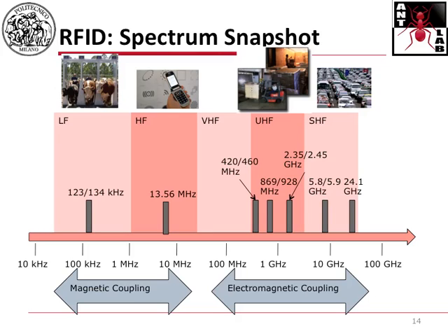Each one of the specific frequency bands has specific features in terms of, I would say, two performance measures. The first one is what range you can achieve in that frequency range, meaning how far can you go from the reader to the tag. And the second one is the specific technique which you use to scavenge energy if you run an RFID system in one specific range.